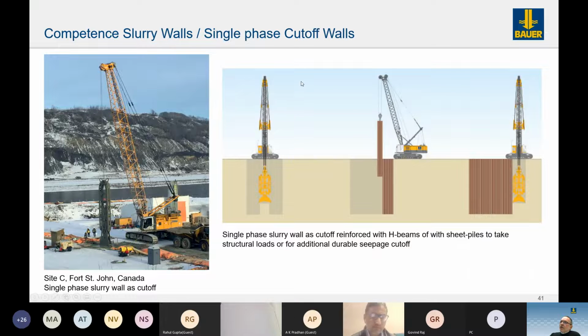For slurry walls or cut-off walls for piles, you will typically not install reinforcement, and also no sealing elements. But in slurry walls, you may install sheet piles to have a permanent cut-off element, adding to it the softer material of bentonite slurry.